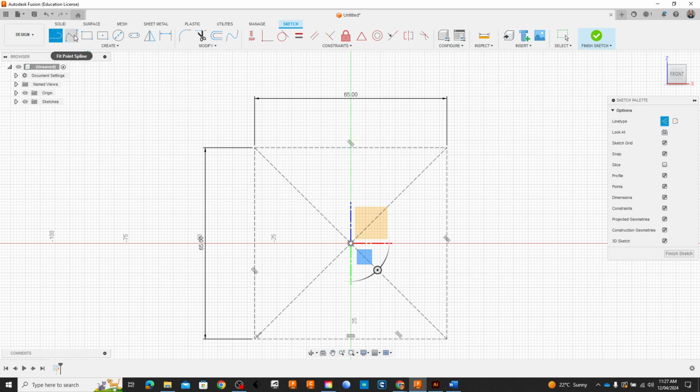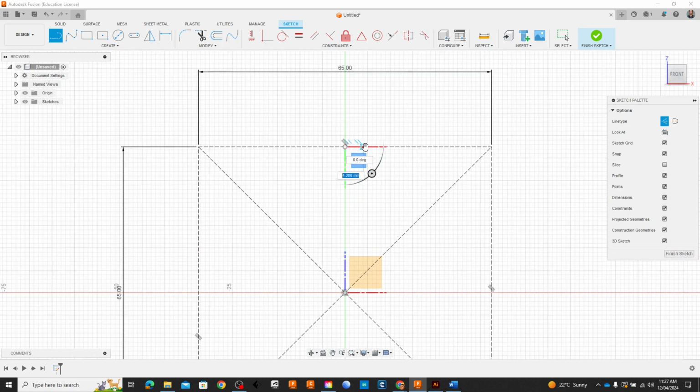If you want to, you can try and use the spline tool, which is like a continually curving line. I'm happy for you to experiment a little bit with that, but there's certain sections you need to have correct, certain parts of your design that need to be correct at this point. First one, we're going to do the stem of the spinning top. It needs to be 5 millimeters, okay?